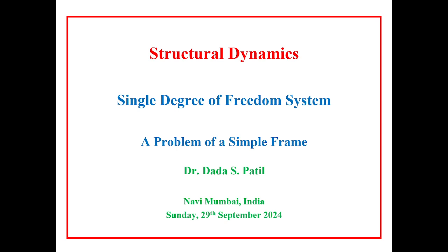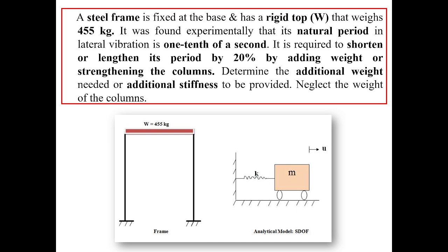Hello, I am going to deal with single degree of freedom system in structural dynamics. Let us see a problem of a simple frame. A steel frame is fixed at the base and it has a rigid top having weight 455 kg. It was found experimentally that its natural period T in lateral vibration is 1/10 of a second, that is 0.1